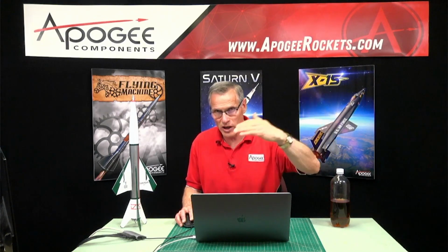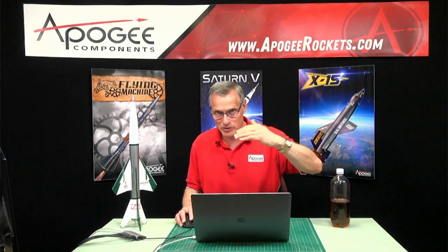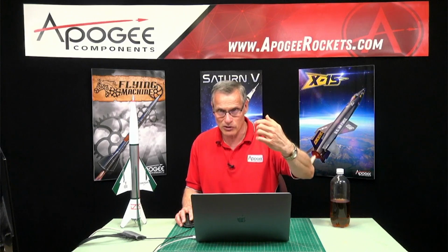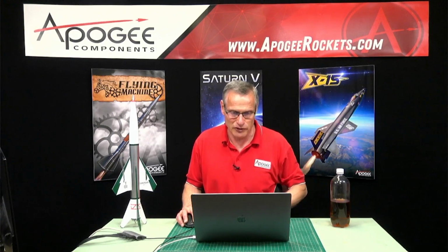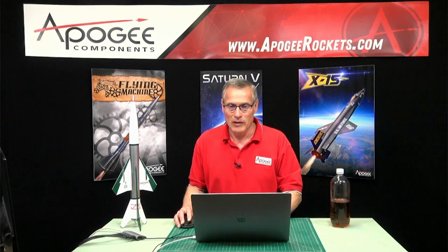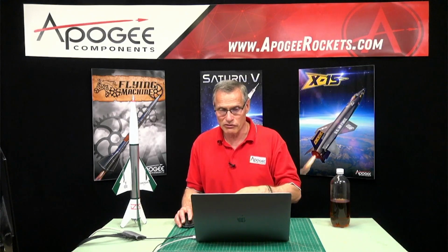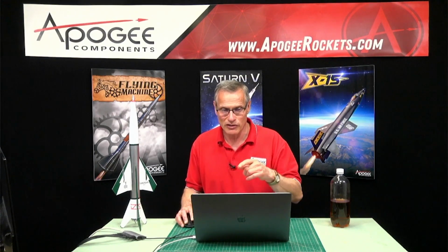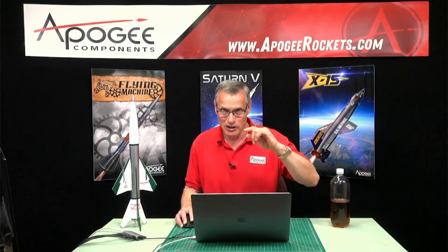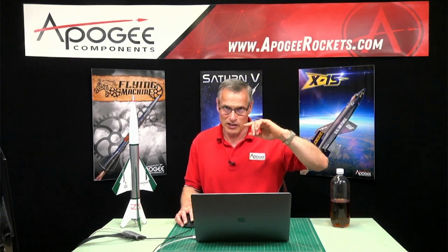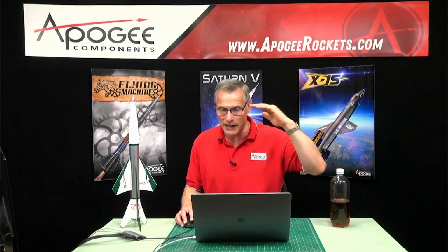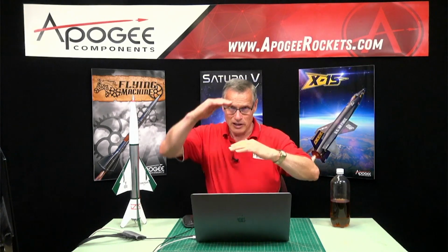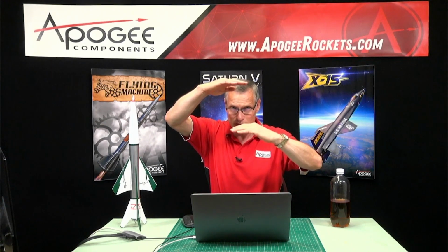So when you get a wind from the internet or something like that, or you're using an anemometer on the ground and you got 8 miles an hour, that is actually at 5,400 feet. So I'd have to type in 5,400 feet based on where I'm launching from. But if I change my launch location, and if I don't change my wind table, now what it's actually saying is 0 miles an hour at sea level and 8 miles an hour at 5,400. So somewhere between those two numbers.